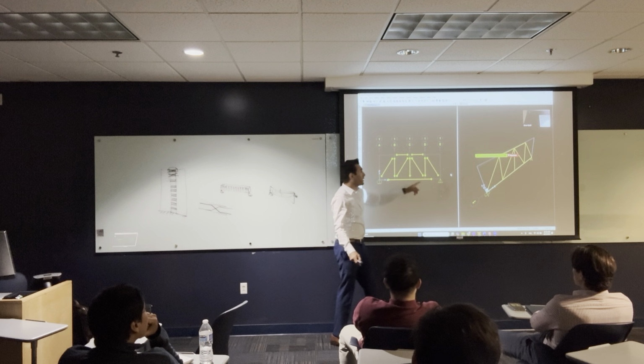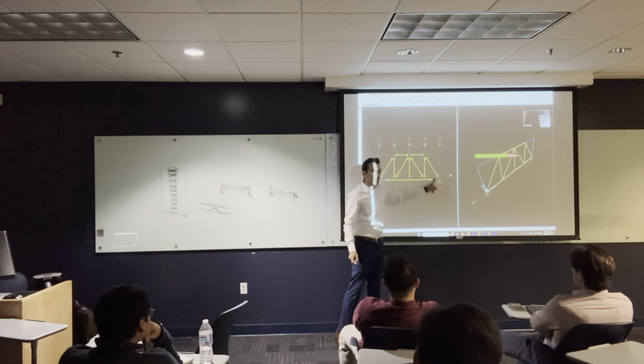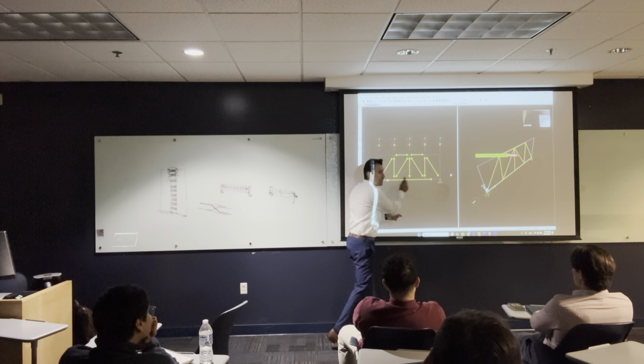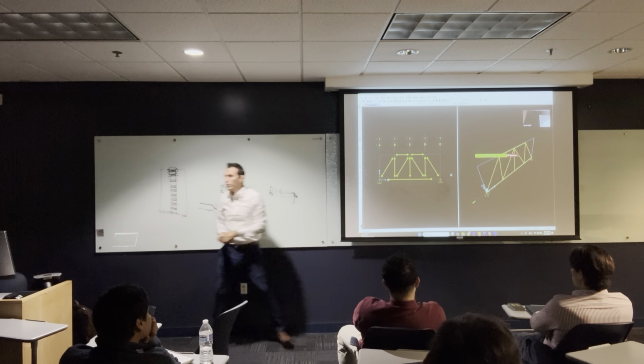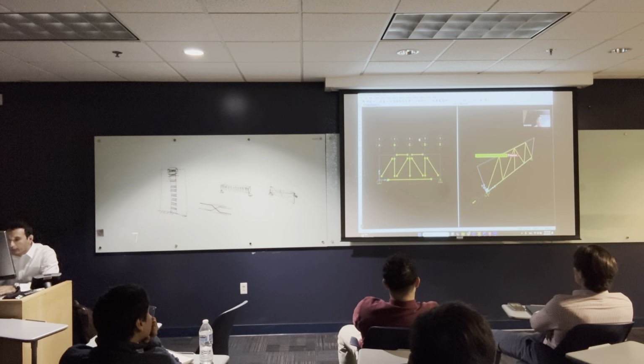The thing is, it's only gonna make the moment equal to 0 here and 0 here, but in the middle, it's not gonna be 0. This is gonna take moment and this is gonna take moment. Okay, so I'm gonna change it for now. Maybe you run it at home and see what's gonna happen if we keep it that way. I'm gonna hit F4.